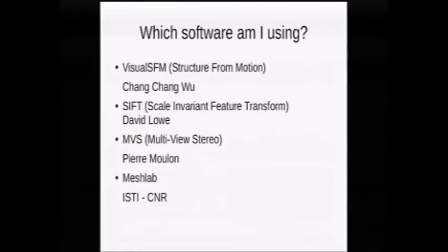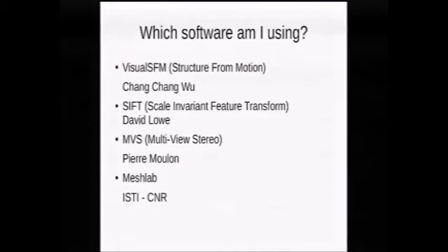We're using primarily VisualSFM and Meshlab. Those two programs work hand in hand to first acquire a point cloud, a three-dimensional point cloud, and then we have to use Meshlab to reconstruct that point cloud in a more coherent way for the computer to understand. VisualSFM is freemium software. It's free to use for non-commercial purposes. The GUI is not open source, but the tools are open source.